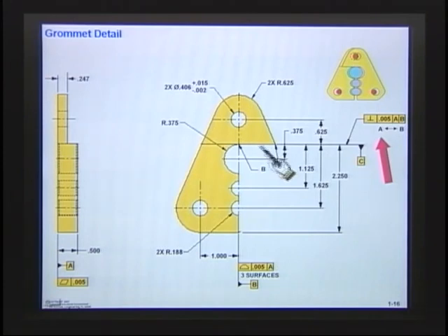This is the surface that's behind. This is a shelf that comes out forward. And I suppose if you put a perpendicularity on, people would say, well, it's not for both. Just to make sure that nobody thought that that perpendicularity goes all the way across, I put a note down here and I said this perpendicularity occurs between A and B. Now if it occurs between A and B, then I have a gap there no more than 5 thousandths. So when I take the two parts and put them together, I should have a max gap there of 10 thousandths, 5 thousandths on the one and 5 thousandths on the other.